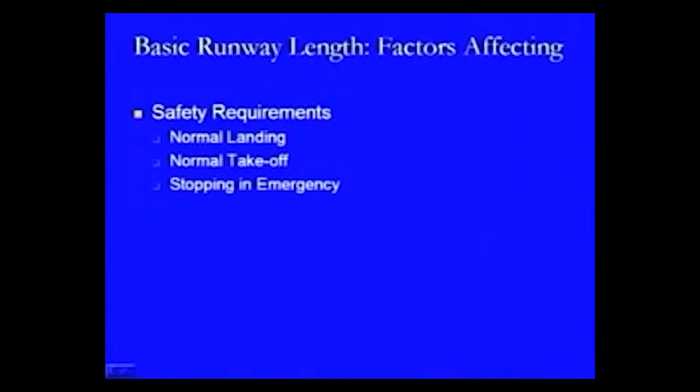So, in those two conditions we require a certain length, and we have to look at whether there is a requirement of increasing the length, or if so, then by how much value that is to be done. Therefore, the three conditions need to be examined: the normal landing condition, the normal takeoff condition, and stopping under emergency conditions.